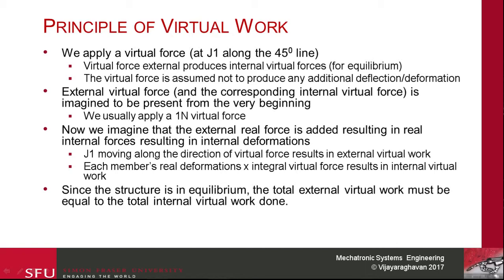We assume that the virtual force produces internal virtual forces for equilibrium, and the internal and external virtual forces do not cause any additional deflection or deformation. The external virtual force and the corresponding internal virtual force are assumed to be present from the very beginning, like the beginning of time. Just for simplicity, we are going to assume that the virtual force is 1 Newton.